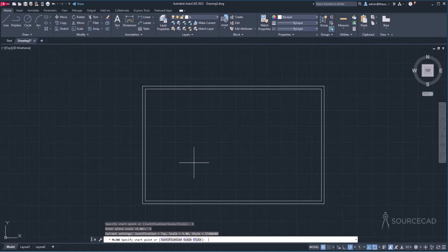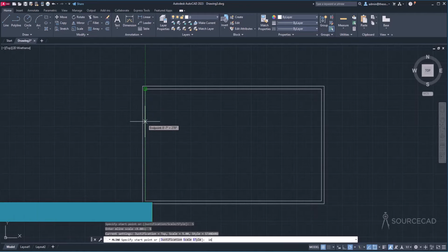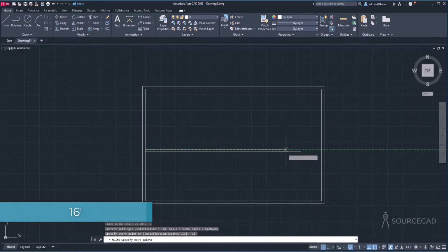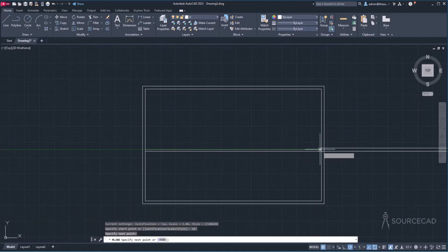All right, now let's make another wall. So from this point, the distance is 16 feet. So I'll simply track this point. I'm not going to click, and simply I'll type 16 feet, enter. Now at a distance of 16 feet, another wall is starting, and I'm just going to click right about here, and we are done. All right, so this wall is added.